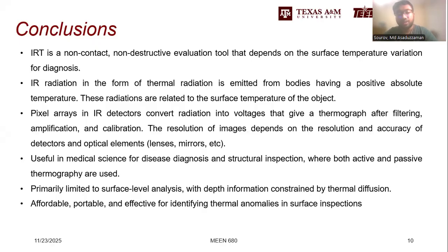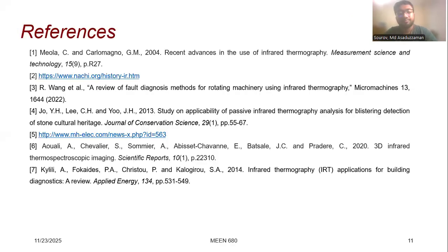Passive and active thermography each offer unique advantages depending on the application, while the technique is limited mainly to surface analysis and sensitive to environmental conditions. However, its portability, low cost, and quick setup make it widely valuable in engineering diagnostics, structural inspection, and medical applications. Overall, infrared thermography continues to be an important tool in modern diagnostic technology.